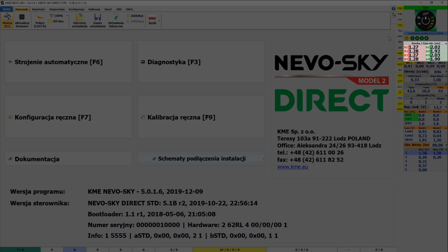In indirect injection, the gas dose is equal to the raw injection time of gasoline. And in direct injection, it is calculated based on the raw injection time and high fuel pressure. In direct injection, it is possible to see the raw injection time. It is given below the dose.